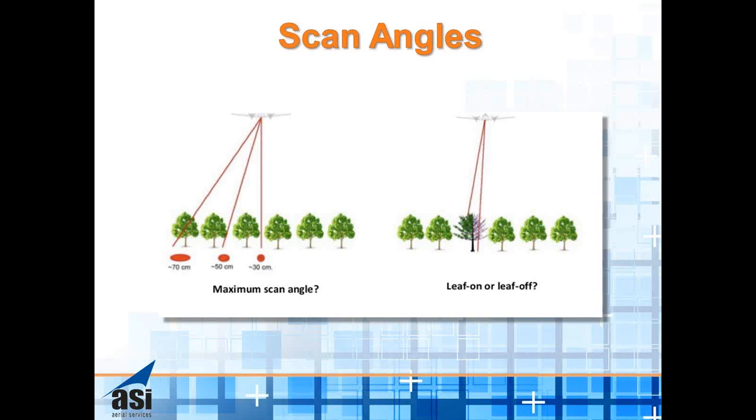There typically are two seasons for LiDAR. They call them leaf on and leaf off. Because we're shooting a sensor that's 300,000 points per second, I can penetrate a lot of canopies where other sensors may not be able to. However, if I'm in a forest and I look up and I can't see sky, I'm not going to be able to penetrate the canopy either.